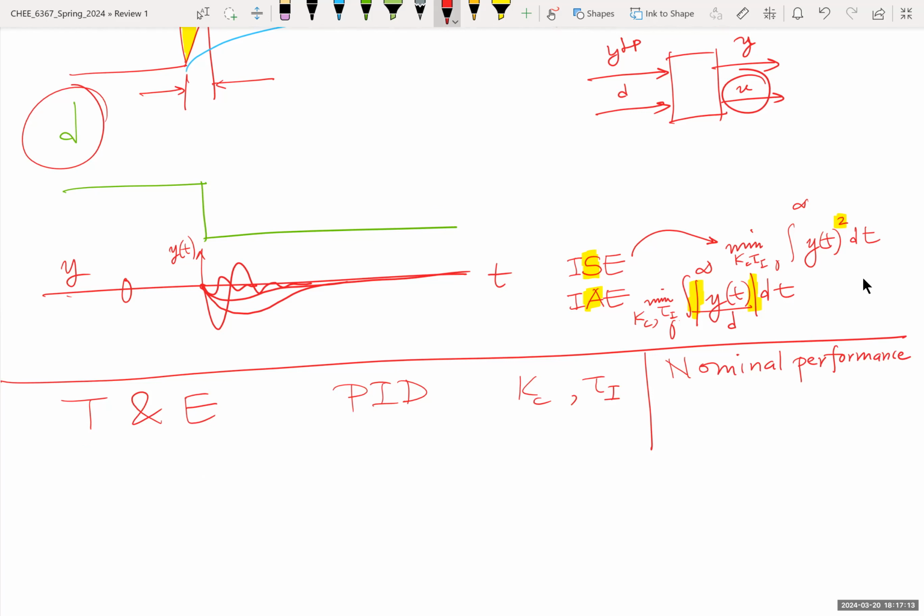Even if my model is super accurate now, down the road, there will be some drifting in my process, I'm pretty sure. So the model is not going to be 100% accurate. It will drift a little bit, maybe a lot. Not to mention that I may even change my steady state operating point. This is done all the time in plants, especially large plants for profit, in which case the model will be off. Is my controller robust?